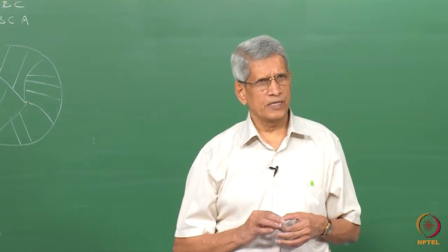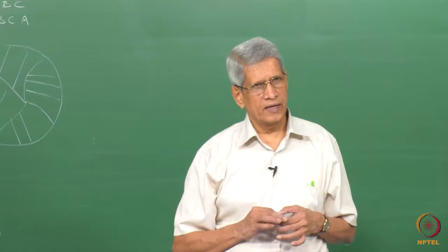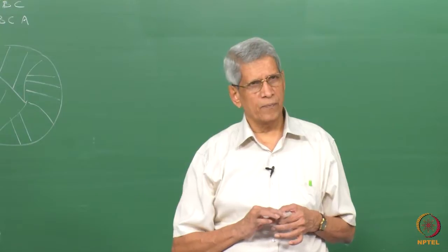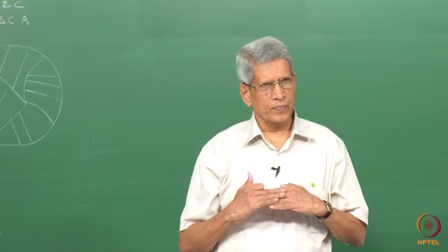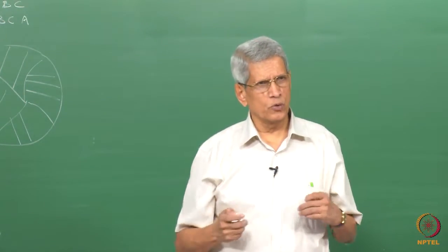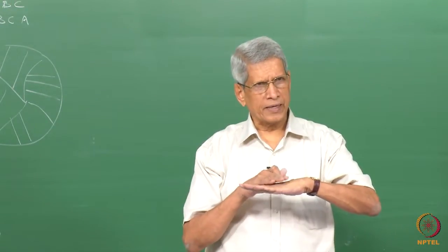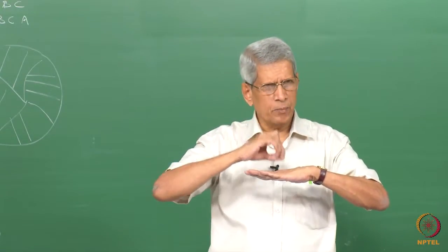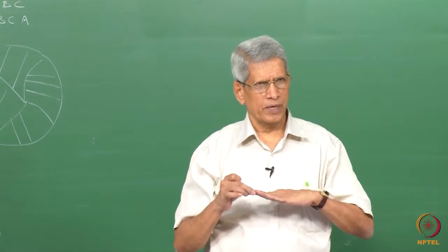In aluminum, if you look at it, twins do not form at all. The reason is that the stacking fault energy is very high. So, whenever one layer after another forms, even during growth, faults do not form. This I believe could be due to the reason that if we look at one layer, a hexagonal packing layer, which is ABC, means that they are stacked on top. If I take an A layer, there is a B site and a C site to which the atoms can go and occupy.